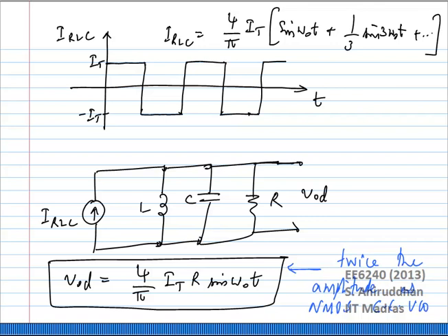We applied this to a pair of switches, right? What is the switching function we used? Let's take the active mixer. We said the output current is just going to be a square wave. So in other words, it has no relation to the input amplitude. The behavior of the mixer does not directly depend on the input amplitude, as long as the input signal switches the two currents completely and quickly, right? We don't care even if the amplitude has small imperfections.